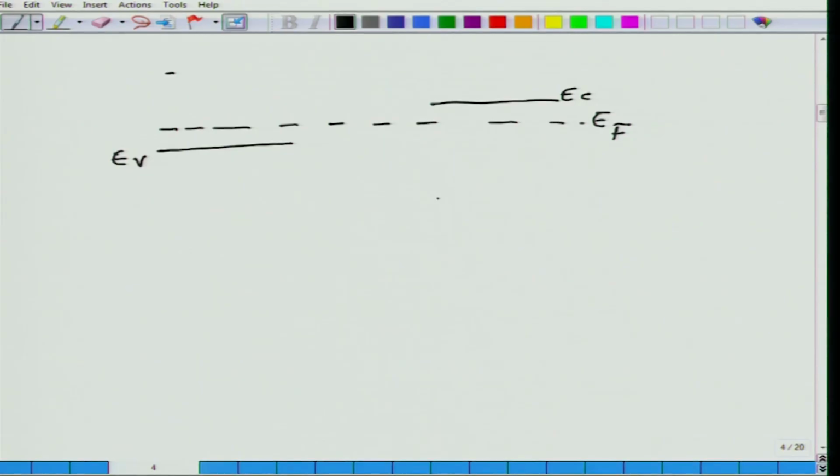And if we try to bring these two semiconductors together, the Fermi level as shown earlier for the p type is towards the valence band, and the Fermi level for the n type is towards the conduction band. In that case, what we need to do is align the Fermi level, because the materials when they are brought together are going to be in equilibrium. And the band gap is same in both cases. Now, what is happening here is this is the metallurgical junction.